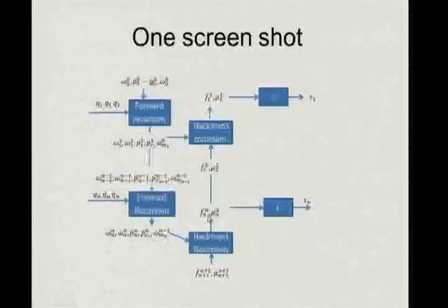Once you have done this, like I needed f_{n+1} and mu_{n+1} to calculate f_n and mu_n, I will need these values to calculate f_{n-1}^{n-1} and mu_{n-1}^{n-1}, and then I keep marching back until I can calculate the forces and moment along the first joint. I take a component and I will get the torque on the first joint. So this is the process by which we march overall.